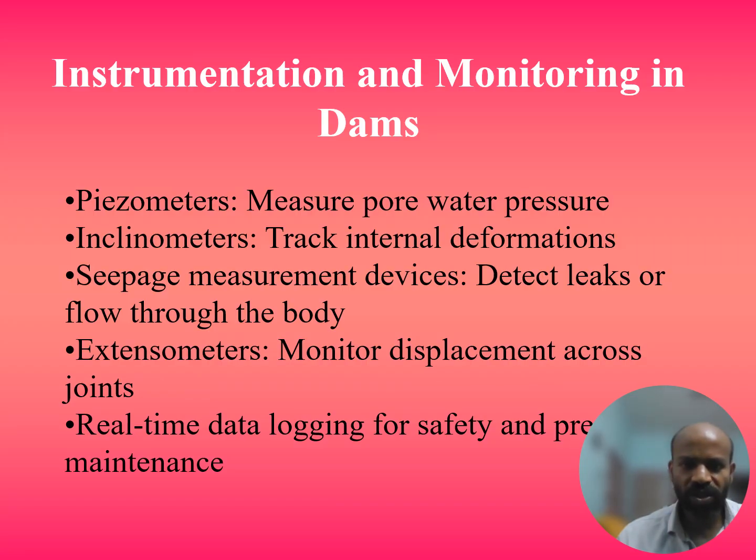Finally, instrumentation and monitoring in dam. Actually, dams are equipped with certain instruments for monitoring the safety of the dam periodically. And the instruments are listed below. Piezometers, it measures the pore water pressure. Inclinometers, it tracks internal deformations, and certain instruments are there to measure the seepage. It is identified by the leakage and flow through the body.